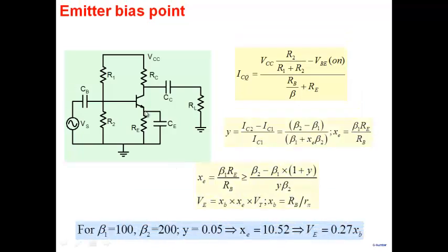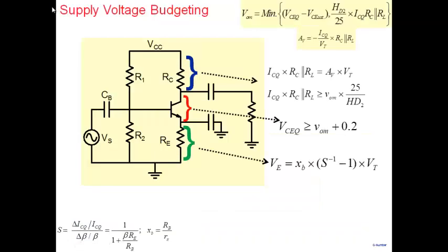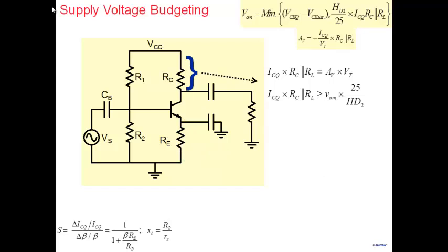How do you choose an emitter bias point? On what basis do you choose? But if somebody doesn't want to go through all of that, then what one may have is a rule of thumb, in the sense, well, let's choose VE equal to 1 volt. 1 volt would be okay, or 2 volt, arbitrary.